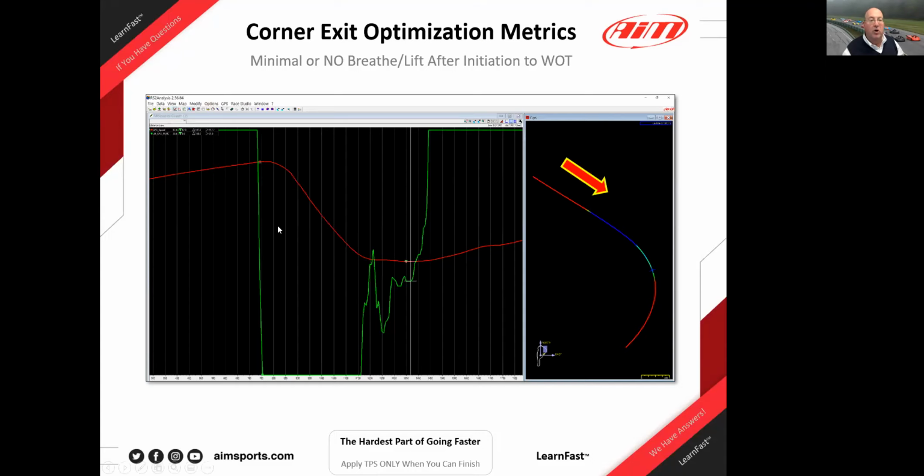But here we have a driver that is going 147 miles an hour into this section, and he's going really fast in. I don't know if I can make my mouse any bigger, but when you pause, it goes off, but it comes back as soon as you start moving it. So you'll be okay. So the issue is we're accelerating fully up to 147 miles an hour. We see the throttle position in green drop. We see the GPS speed drop in a linear way. And then we see an ease off of the brake pressure result in a leveling out of the speed. The deceleration is going away.